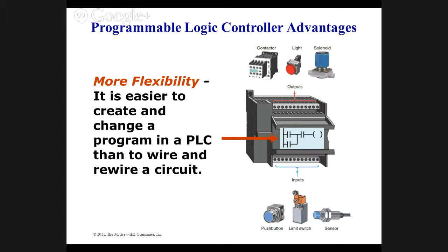So you say that you can stop the... If all your devices are hooked to a PLC, the only limit to what you do with it is your program, which means any combination that you want to do, if it's hooked to a PLC, you can change it to make it happen. So while it's still running? While it's still running, yes. Now, I don't guarantee there won't be a mess after you hit accept, but you can do it. There are some safety concerns and different things in there you have to watch out for, but it is possible.